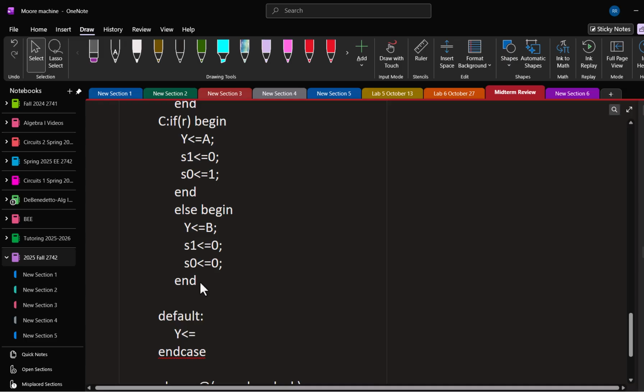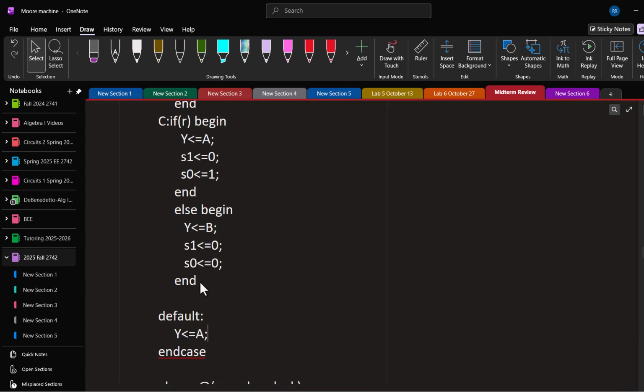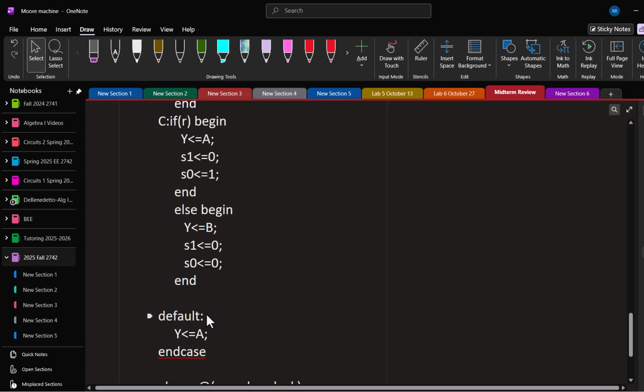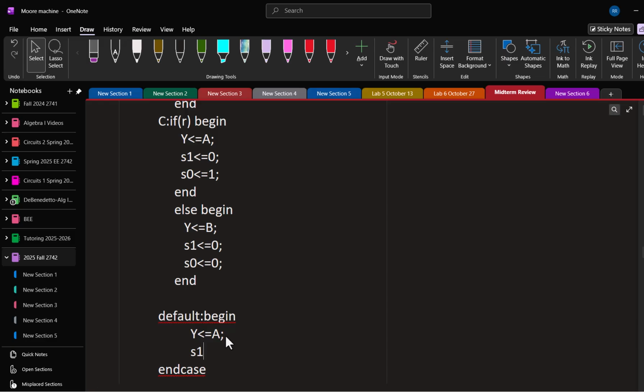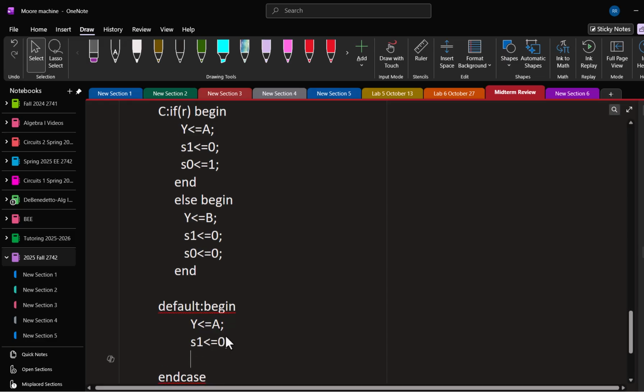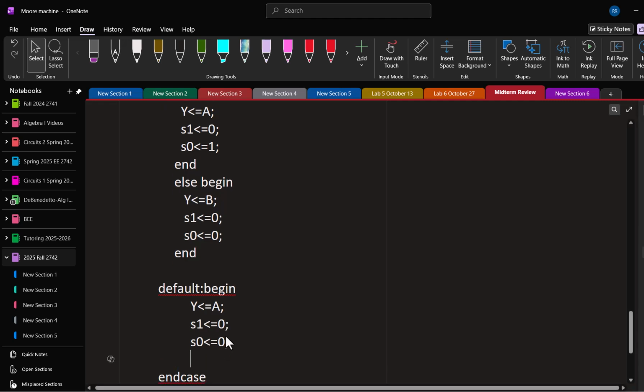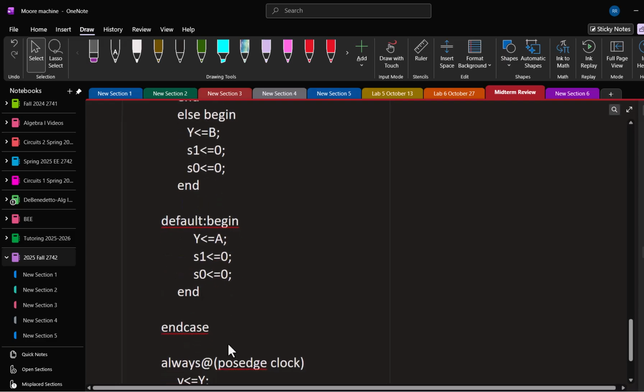Y becomes equal to, and you can either set something. I need to have a begin and end here because I'm going to be defining more than one thing. Begin. If I didn't put this in here, Verilog would fuss and say you have a possibility that something's not going to be assigned. Yeah, definitely has to have a default.